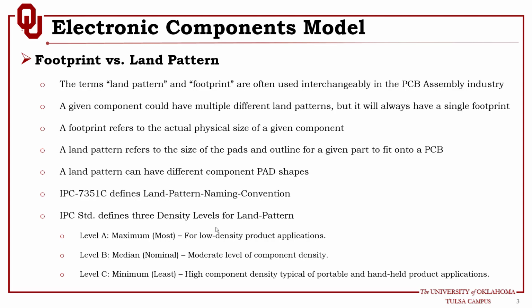The reason for that is providing good solderability of the printed circuit board, because if you design the pad to be the same size as the lead, there is no place for the solder to go around, and these pads will be prone to manufacturing problems and issues during production. That's why they differentiate between footprint and land pattern.